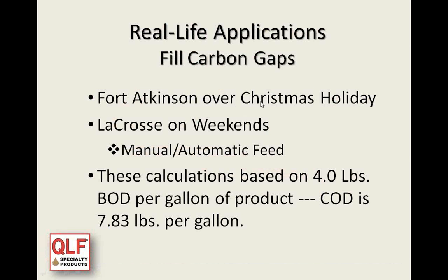They use the fill gap method. They do it at Christmas time and when industry shuts down. La Crosse does it on weekends, and they do manually and automatic. You can use 4 pounds of BOD per gallon for doing calculations, and COD is about 7.8.